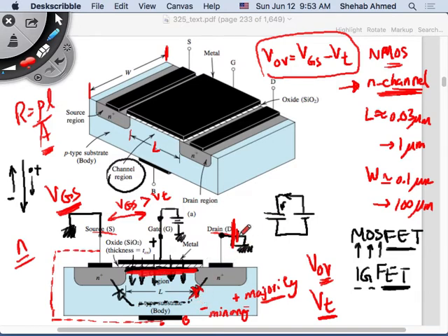So there is a component of this electric field in this direction, and let's say an electric field emanating this way out of this drain across the device. This has a component this way and a component perpendicular to it, right? This is due to what? Drain-to-source voltage. So this is a component of the electric field due to the drain-to-source voltage. There's another component that I will not bother with because I have a reverse bias diode here, so I will not care about that.